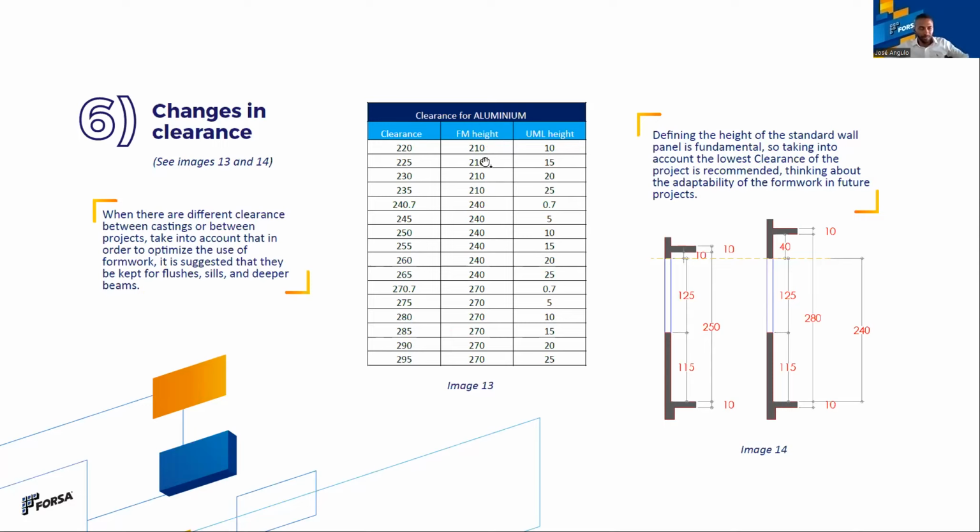So these 30 centimeters are going to be checked all along the column. Check this one, 2.1, 2.1, 2.1. Then you go to 2.4, 2.4, 2.4 meters, and then 2.7, 2.7, 2.7. It means that the standard heights are preserved in this central column, and the main changes are based on 30 centimeters.